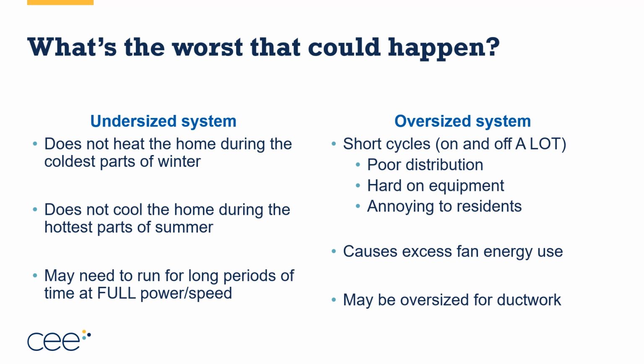But that central air handler fan, when these things are oversized, modern ones have what are called electrically commutated motors, or ECM. What happens with an ECM is when it's trying to push through undersized ductwork compared to the size of the system, so an oversized system for the right size ductwork, it's going to encounter static pressure. Now, static pressure in ductwork is the pressure trying to go outward everywhere, which is different from velocity pressure, which is trying to push it down the ductwork. The static pressure is the part that's kind of, if you imagine a balloon that you've blown up, it's the pressure on equal range all the way around that balloon.